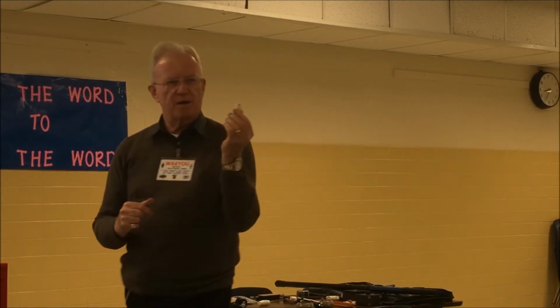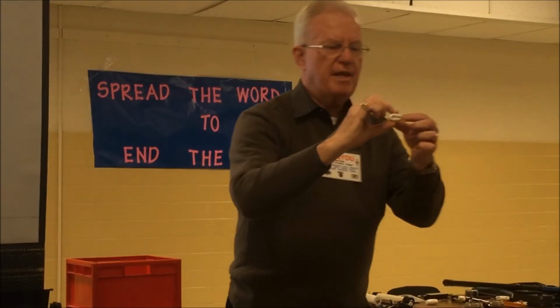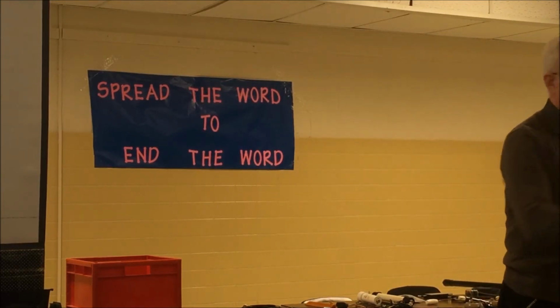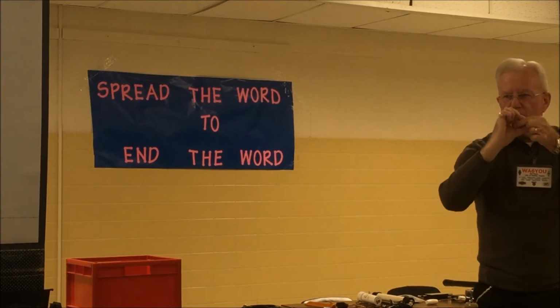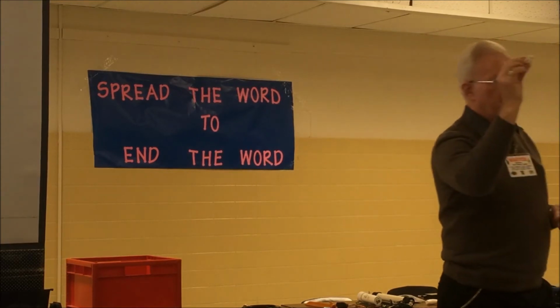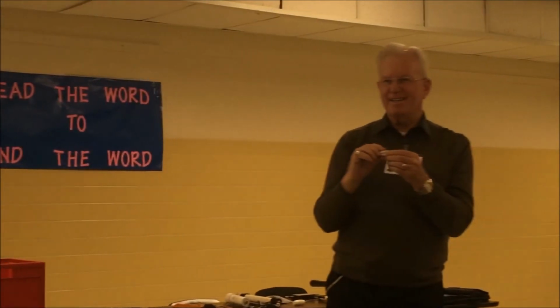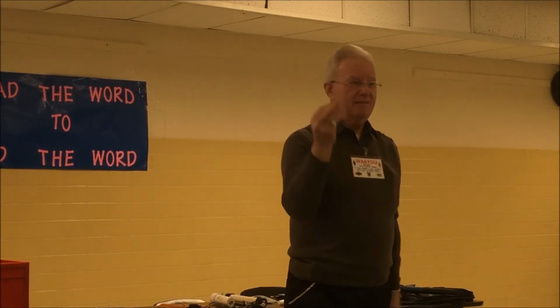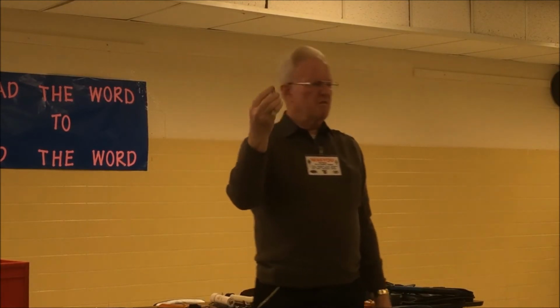Guys, I don't know if I mentioned it last time, those of you that attended the first session, don't use these on the end of your dipole if you're using wire for a guy. If you're using nylon, it's fine, but with wire you get a heck of a capacitive effect from the wire guy on these. And you know the purpose of these originally? If it broke, the antenna didn't come down. That was the purpose of these. But hey, you just don't see anybody using these anymore.